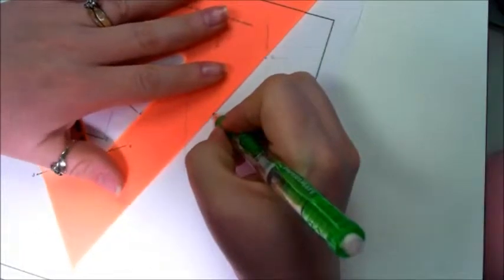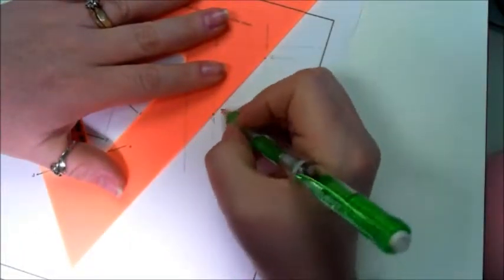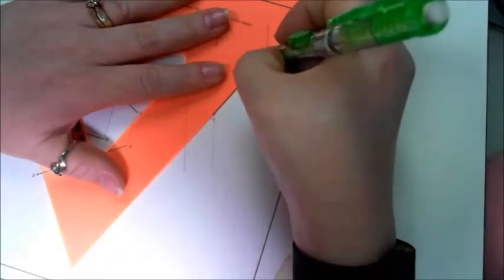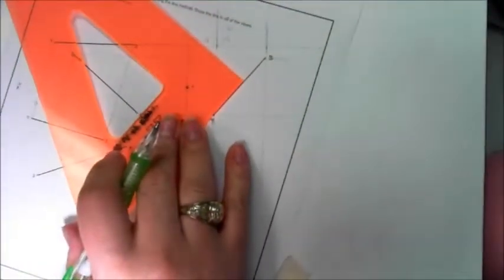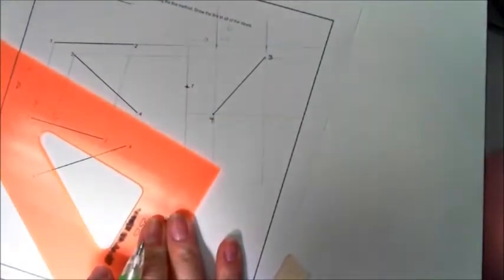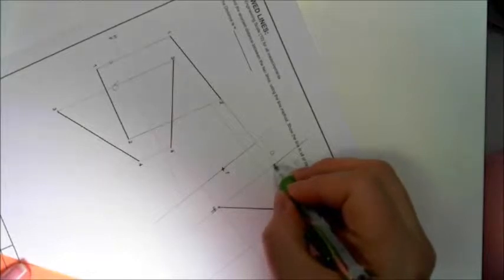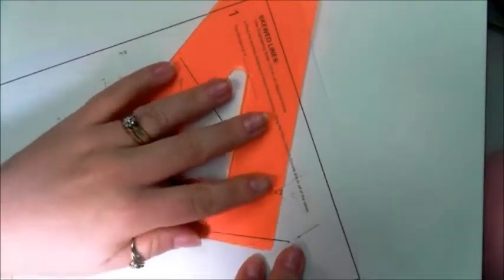Why is this important? Because we're going to make this perpendicular to find the shortest distance. So we now have 3, 4. We want a perpendicular that fits here. So I'm actually going to untape it for right now and make it a little easier so I can move it more to the screen. So we now want a line that's perpendicular that hits that 1, 2, but perpendicular to that line 3, 4 to get that actual shortest distance.